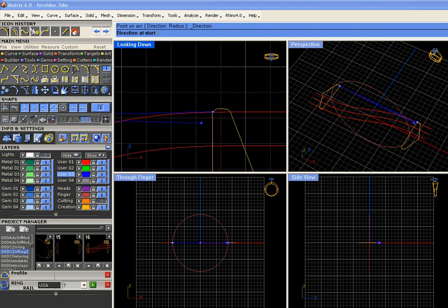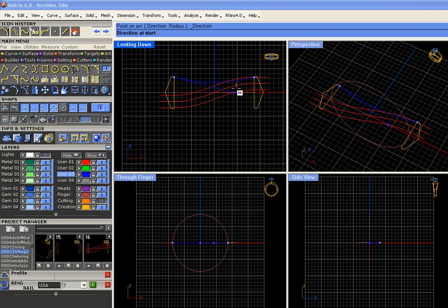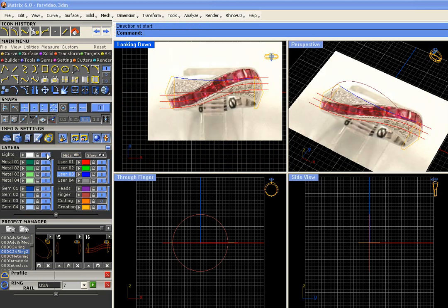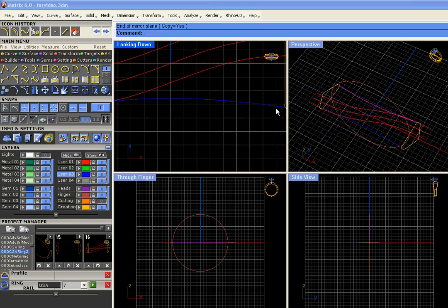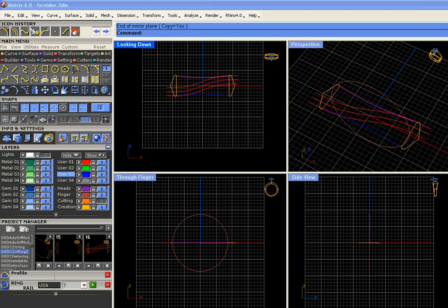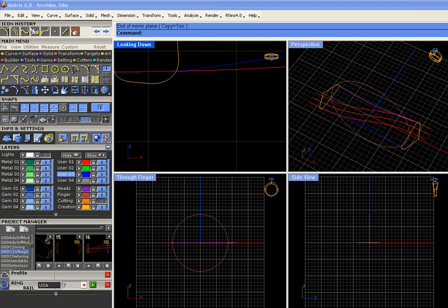So just stop there with a left click, and then draw this in to just kind of a gentle curvature for the side of the ring. We can look at our picture again and make sure we're getting it. Pretty good. Okay. We can mirror this, F4, Shift, and click. And everything should touch because we mirrored the profiles.